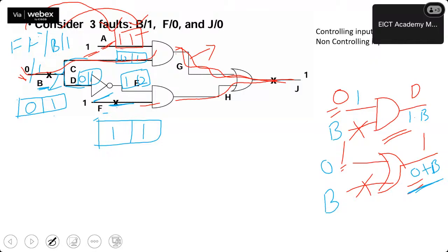So here the first one is 1, 0. So this is going to give me 0, meaning fault-free was expected to be 0. But what is the faulty value? For A it is 1, and for B also it is 1. So the faulty value becomes 1. So I'm expecting the output 0, 1. Fault-free and faulty. Let's come to the next one.